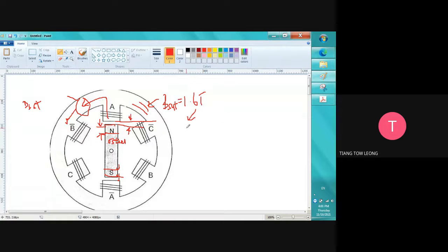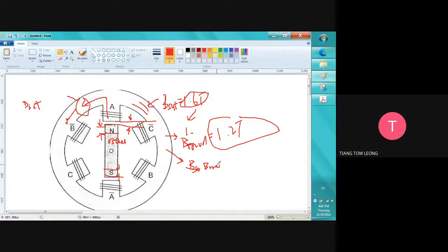It won't be too low. Too low means maybe the motor that we design gives the V mode, about maybe 1.2 Tesla. Then it will be under design, because it has not reached 1.6 Tesla. If at the optimum, the motor that we design gives V mode, the modulus magnetic flux density, about 2 Tesla, which is more than the 1.6 Tesla, then it is over design.